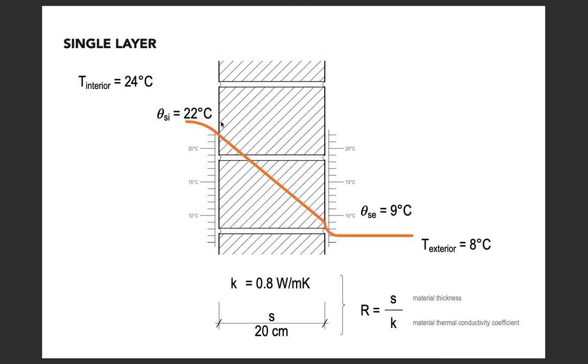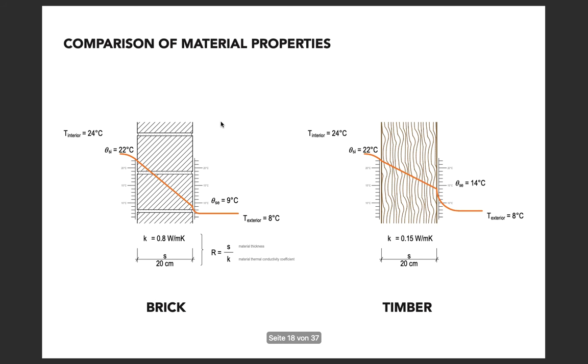There's actually a graphical way to express the development of that thermal conductivity within your construction, by having a temperature scale on the inside and on the outside, and you can show how that is transmitting through that material in a graphical way. And then that becomes really helpful in comparing two materials as well.